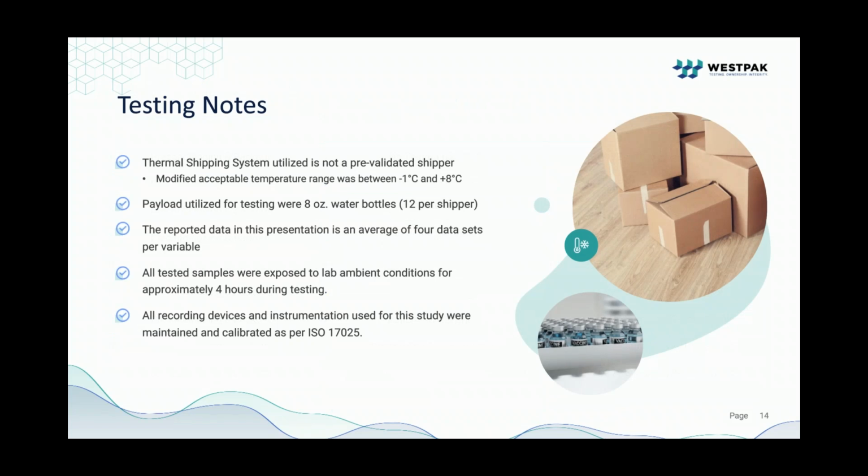Just some quick notes on the testing conducted. We did not use pre-validated shippers. The typical acceptance criteria is -1C to 8C, which we kept in mind when assessing the thermal performance. Our payload was 8-ounce water bottles, 12 per shipper. The reported data was an average of 4 data sets per variable case.